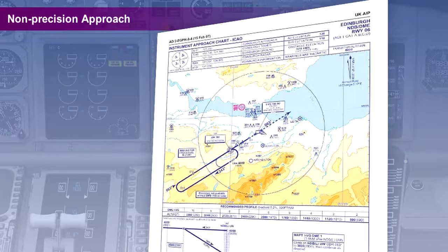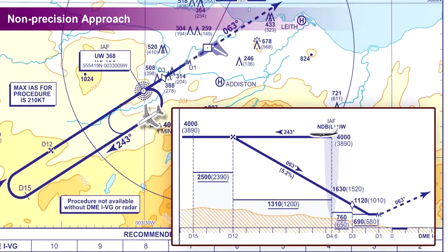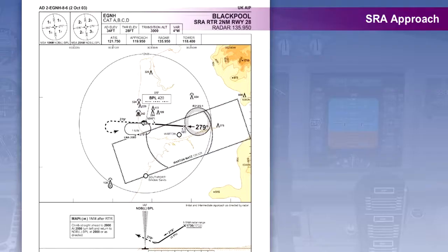Where no ground equipment that can provide height data to the aeroplane exists, the procedure is defined as non-precision, although the track guidance may well utilize devices that would serve a precision approach as well. Non-precision approaches are normally provided with track guidance from VOR or NDB equipment, but might utilize the track guidance data from ILS localizers or PAR azimuth equipment.